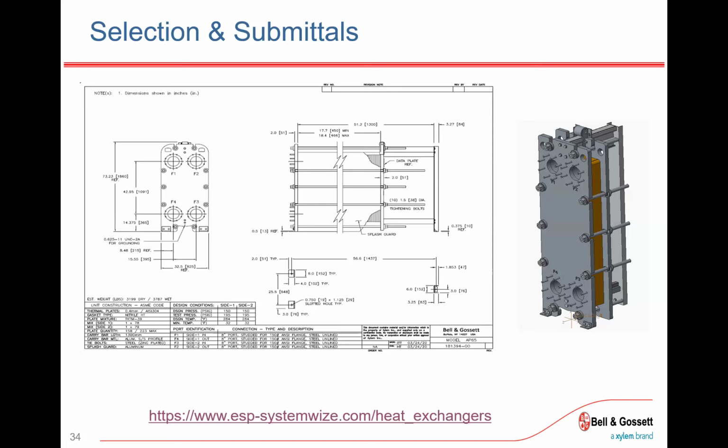So I usually look at percentage of end of curve. Obviously, you want to know your pump speed, because if that motor is rated for 1800 RPM, I don't want to have a selection even if it looks like it's at a nice point.